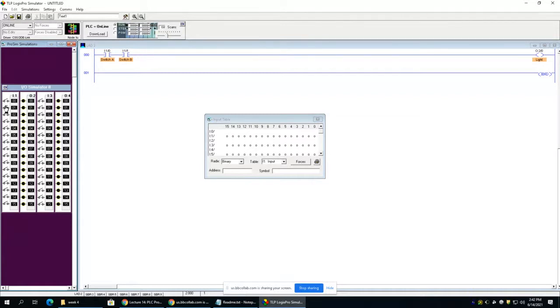Now watch what happens when I close this. I'm going to close input module 1, bit position 0, 0. If I close this switch, and then I look over here in the table, there's a 1 here now representing that switch close. Your program that you write is not looking at these switches. It's actually looking at, well, it's looking at the switches and it's updating this table right here with the 0 or 1 depending on the state of this.